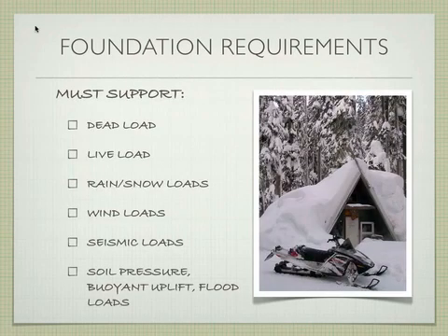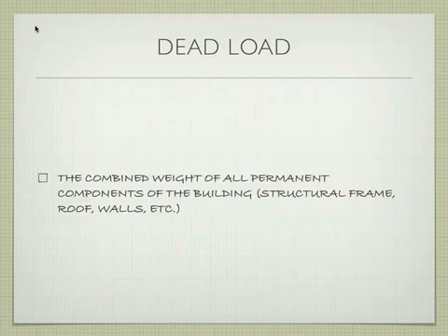Okay, so Chapter 2, Foundations. First one's always tough. A foundation is what's underfoot, and it needs to be able to support what's called dead load. It needs to support live load, rain and snow loads, wind loads, seismic loads, soil pressure, uplift, those sorts of things. So it really deals with a lot of loading conditions, and it's really important in a building. Let's talk about the individual loads specifically so that you understand each piece.